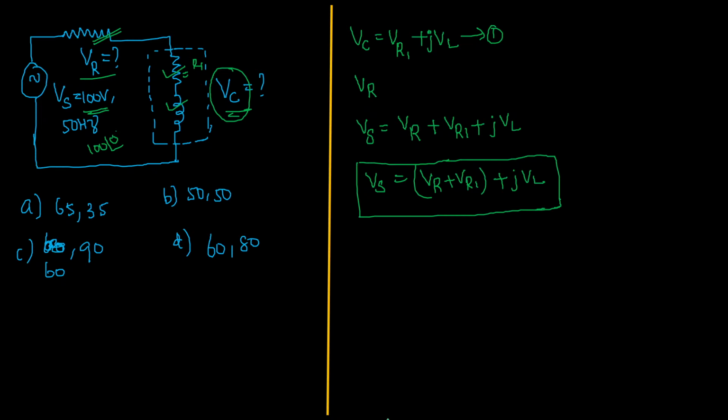So from this, how will you write this expression? This expression can be written as the real part VR plus, only magnitude I am focusing, real part squared plus imaginary part squared. We should keep all this under the root. That can be considered as the supply voltage. Am I right, sir? This is the actual truth. They only gave that the value of the supply voltage is 100 volt. So we can substitute 100, or you can also go with the options.